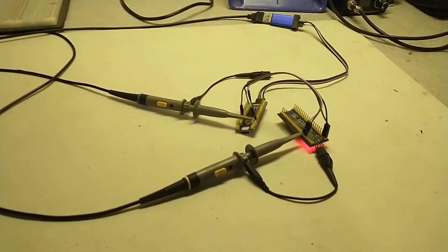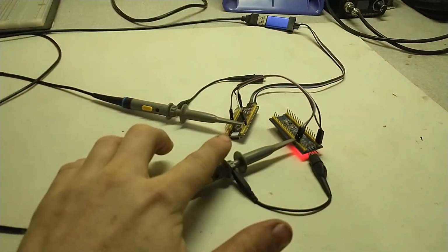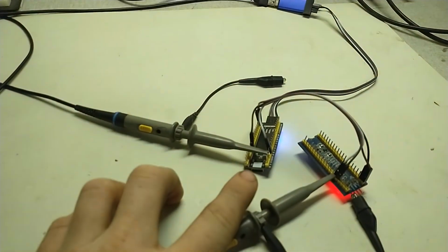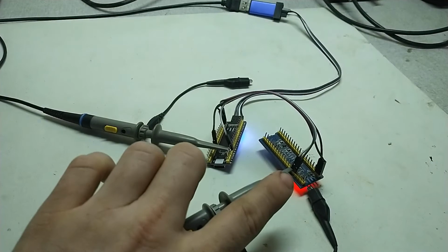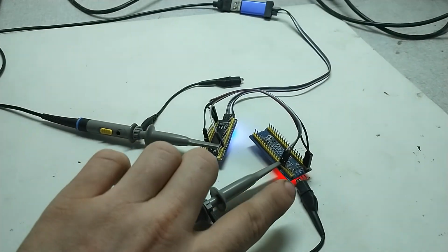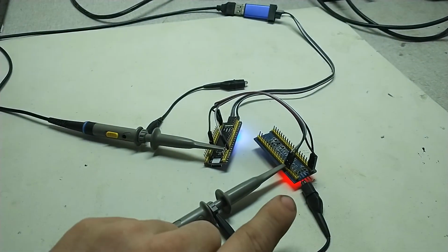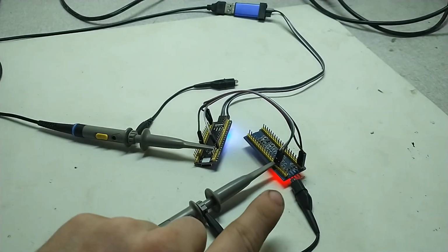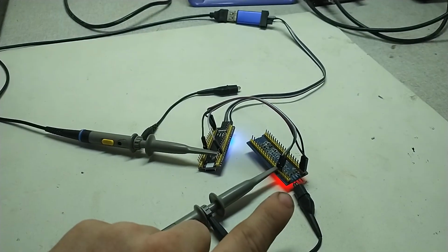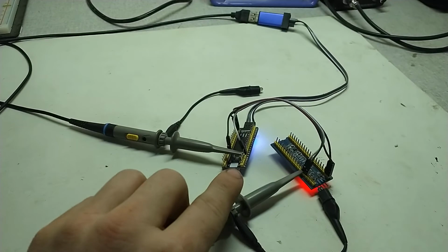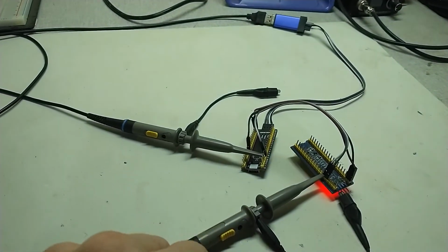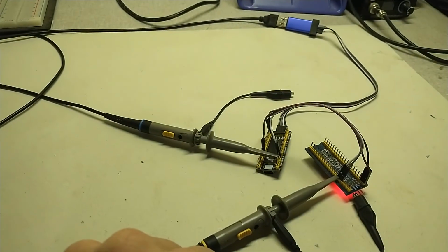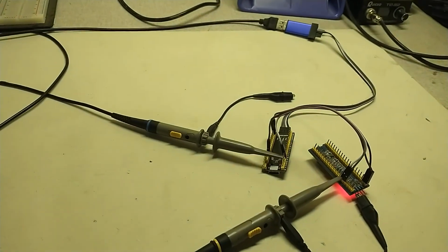So I've got this set up on the bench. You can see this is the STM32F401C board, the black pill, and then I just have a STM32F103 board over here acting as a cam and crank sensor emulator. You can see the LEDs blinking, and that's actually blinking from the time scheduler that I created.